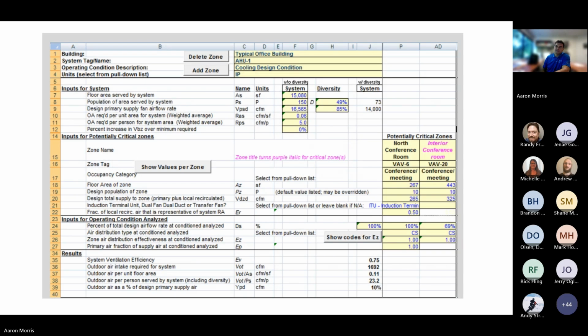62.1, they call this the 62.1 MZ calculator. This is a spreadsheet tool developed by ASHRAE that comes with that user manual, and it provides you with data tables on separate tabs. They give you the max values, concentration limits for various contaminants, and give you outside air contaminant levels based on different cities. So lots of useful information. And then on this page, you would plug in your inputs, and it would help calculate by zone.